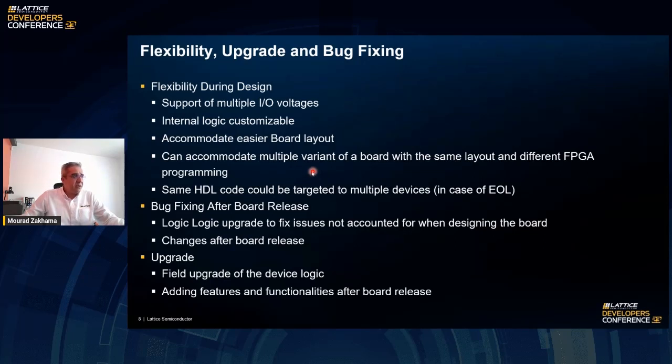The other thing is the same HDL code could be targeted to multiple devices. Once you have the design done, it's operating on a device. If the device goes to end of life, you always have that source code that you could target to a different device and have a quick turnaround in terms of getting a new board released.